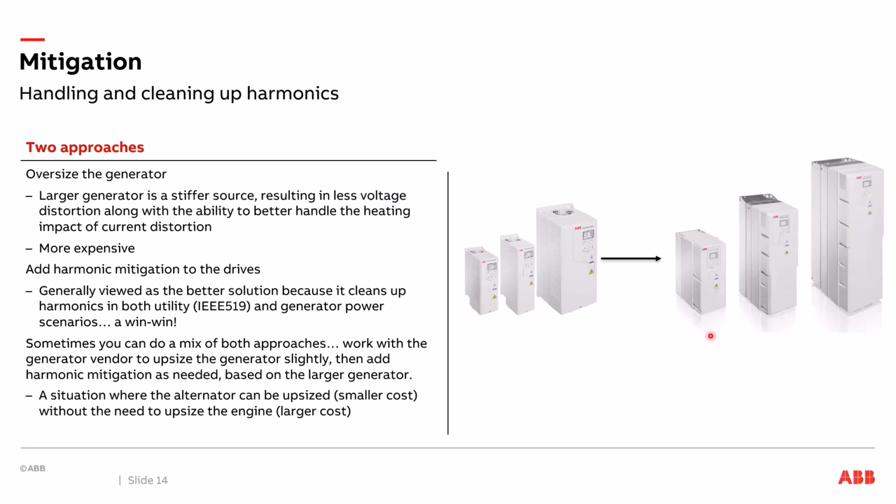It doesn't have to be active front end drives. There's passive filters, there's adding extra impedance. You do the harmonic analysis, figure out what makes sense for your building, your application.